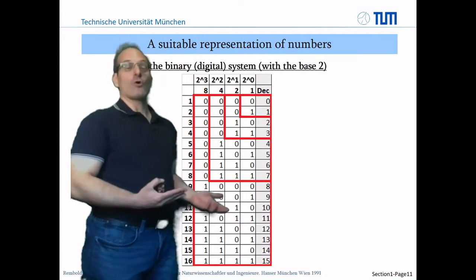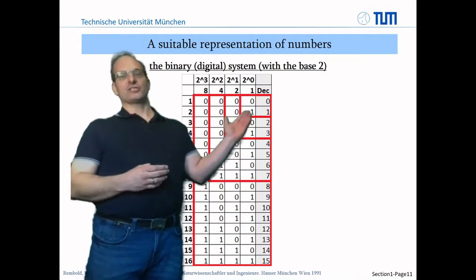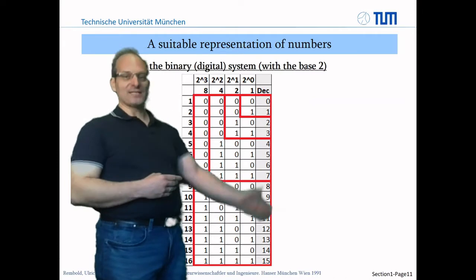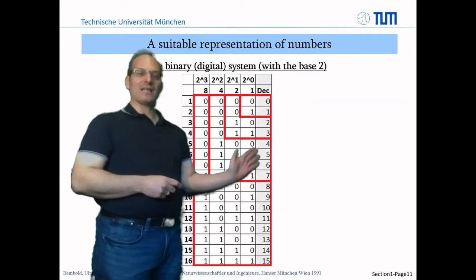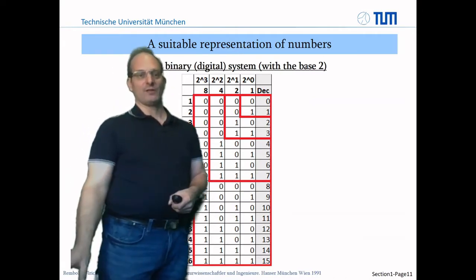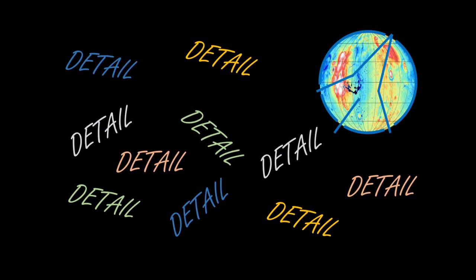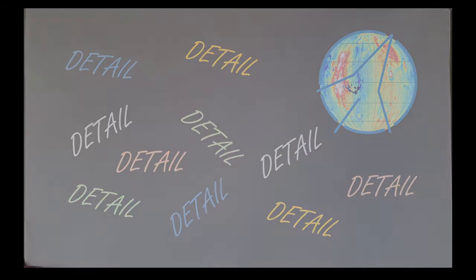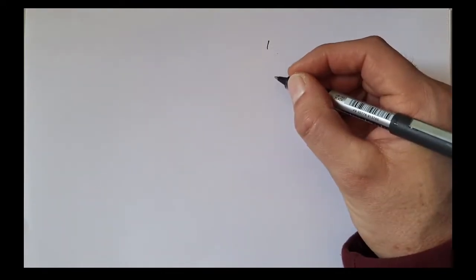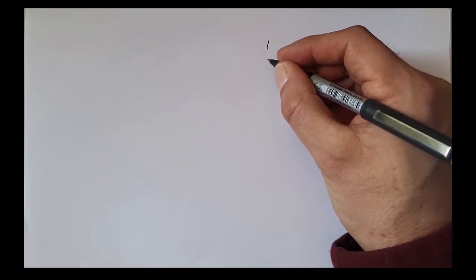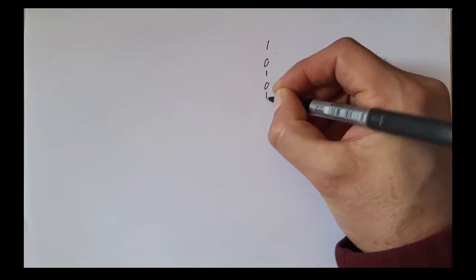So you can represent all possibilities with such a table, where you have all possibilities aligned. And this table can be created quite simply, and this I want to show you. It's quite simple to create such a truth table. You just start with position 1, and then you toggle the bit 1 by 1.